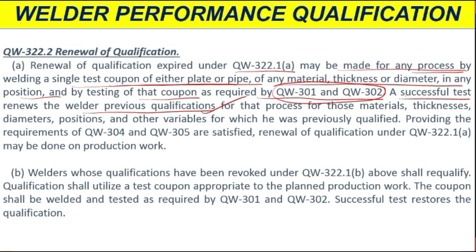For that process, those material thicknesses, diameters, positions, all these things, it renews the previous qualification, provided the requirements of QW 304 and 305 are satisfied. If QW 304 and 305 are satisfied, then it also renews the previous qualification.